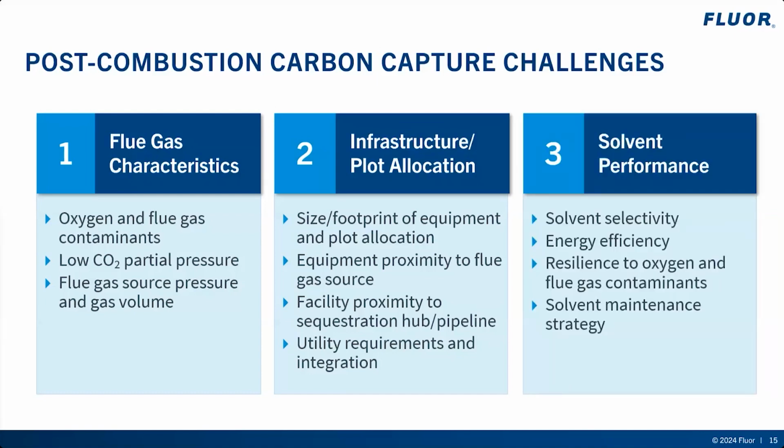Third is solvent performance. Low CO2 partial pressure drives a requirement for solvent reactivity, but the solvent formulation will also need to address selectivity to ensure the final CO2 product quality requirements are met. Maintaining solvent quality is the key to consistent long-term carbon capture plant performance.